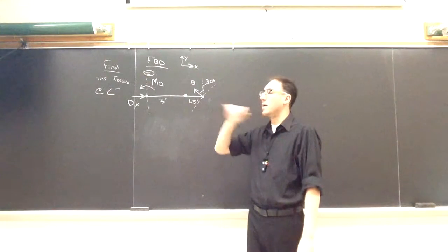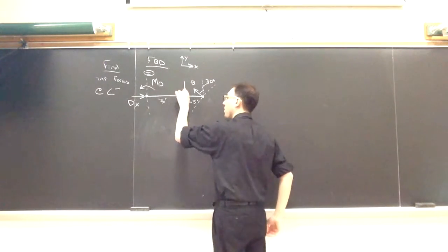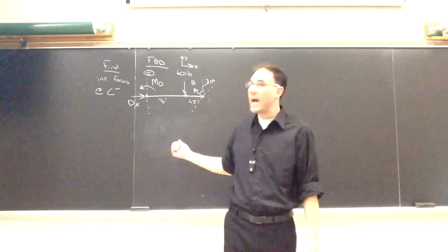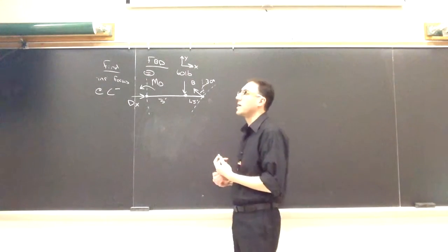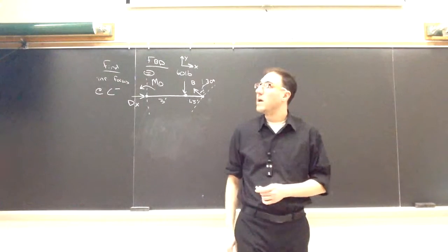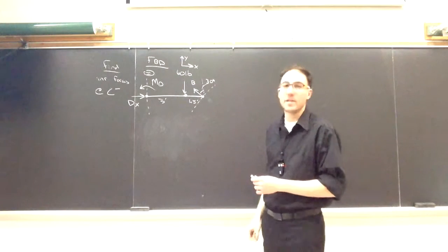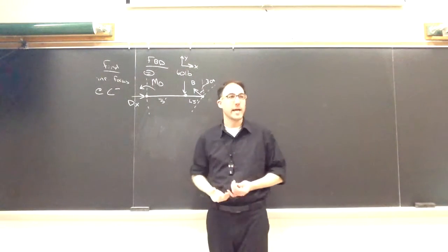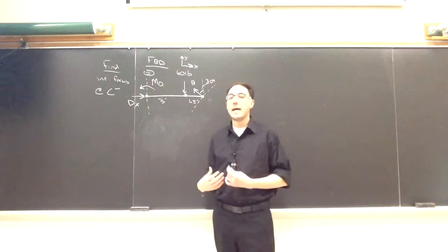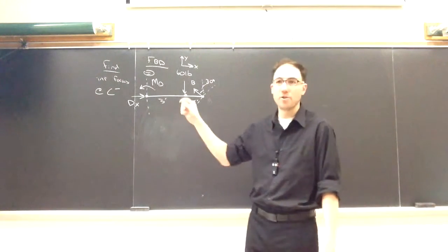We have one triangularly distributed load, and we have a point load. I'll just copy the point load down here of 60 pounds. In my external picture, I can simplify the distributed load into point loads acting at the correct locations. In this case, if I look at the whole triangle, DB, with the apex of 15 pounds per foot, I could treat this as some scalene triangle. I could find its area and try to find its centroid. I would say it's probably easier, at least at this step, to treat it as two right triangles instead.